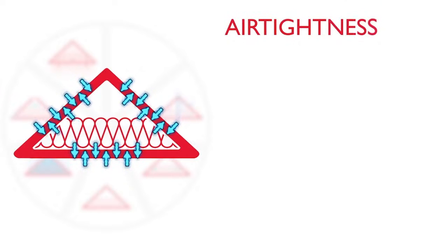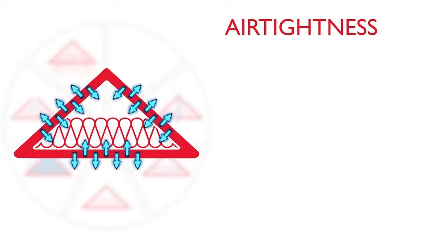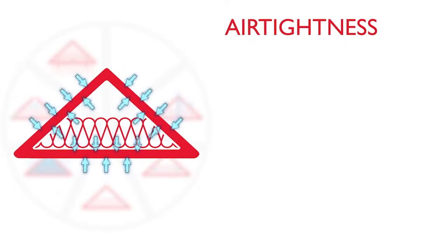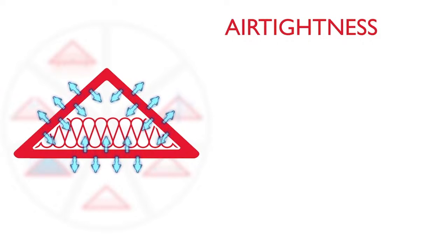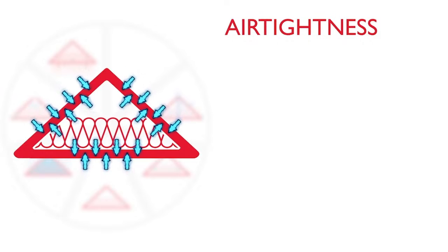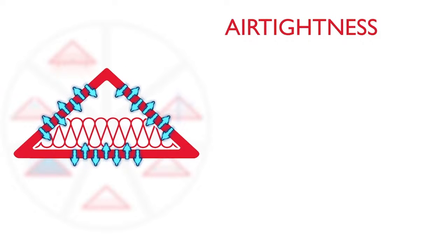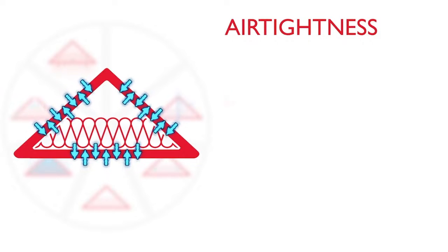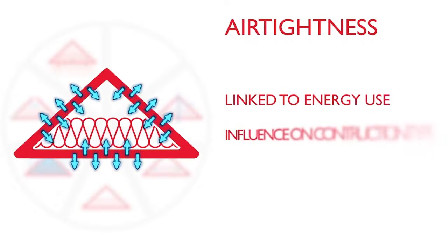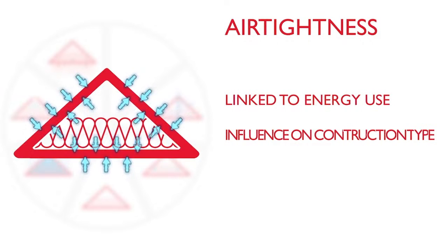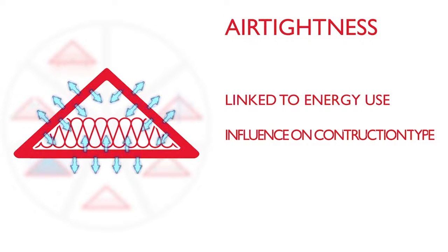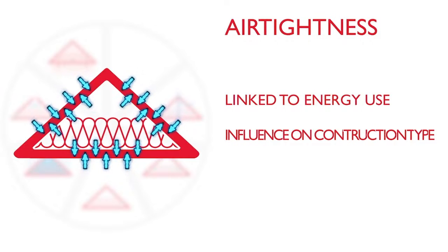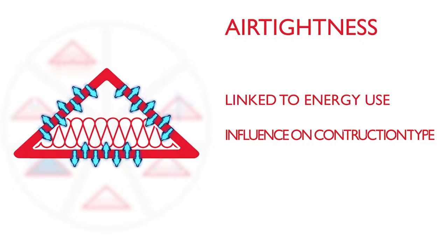Airtightness of the roof. The airtightness of the overall roof construction, as well as the individual components, is also an important influencing factor. Whilst the vapour drive present in a project establishes the question of what condensation risk is present, the air leakage rates involved begin to help to shape the best answer. If the energy performance assessed in SAP or SBEM calculations require a low air leakage rate, that may influence the choice of roof construction or the components specified.